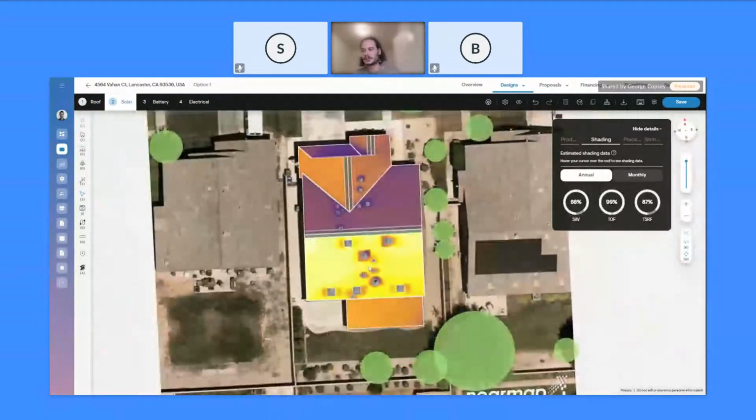So as I say, the shading heat map may help you. This is a pretty simple roof. We've got a very big south-facing facet here. This is probably where we'll put our panels. But if there is a doubt, do run the shading wizard just to give you that TSRF. Setbacks, if you want to play with it, you can, but more often than not, it will be there.